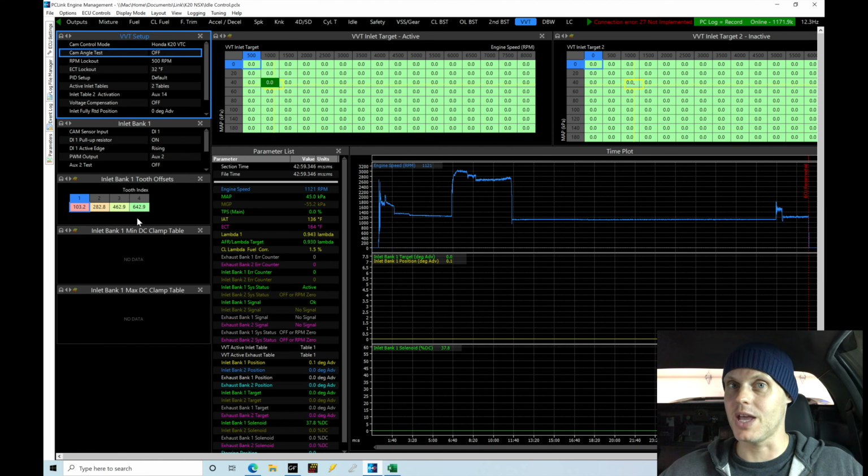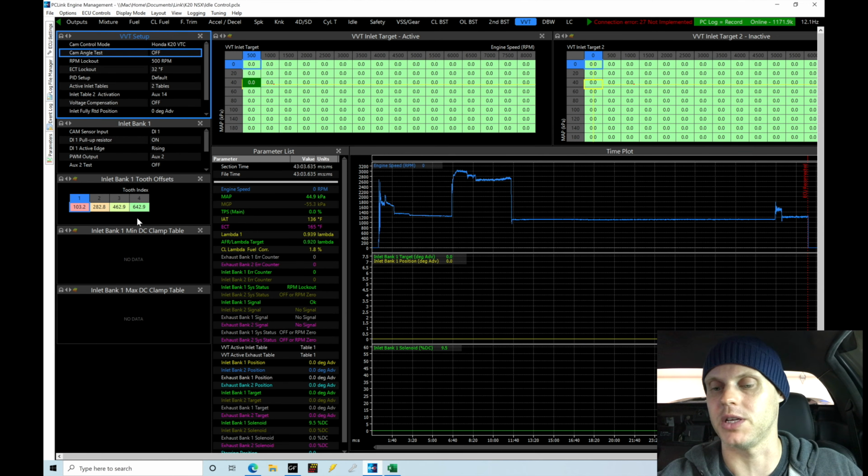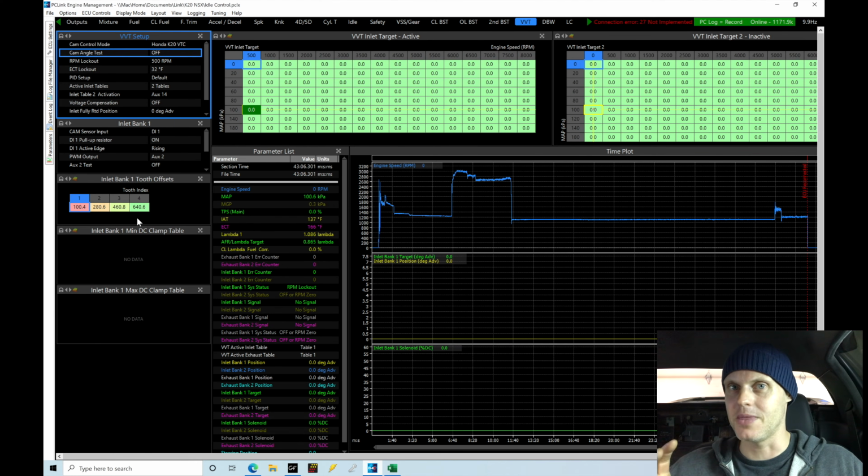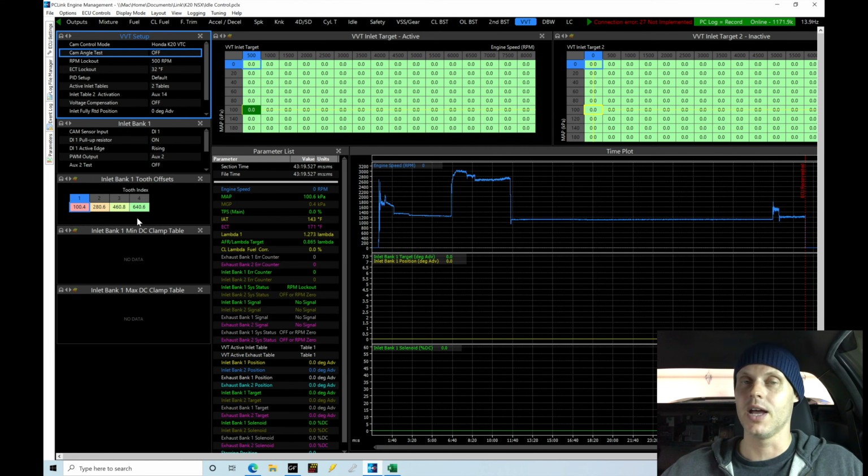So that's going to be it here, wrapping up, taking a look at everything in our tutorial. Let me shut off the engine so we can talk a little bit easier. Again, the goal of this video is really proofing what we built in the base map creation, catching any mistakes that we have, and making sure that everything has been validated so we're able to fire off the engine, have it hold its own idle, and then being able to have something like variable cam control validated, inputs and outputs all validated, and then we can move into the actual calibration process, looking at part throttle calibration, looking into full throttle calibration. We have a lot left to cover here.